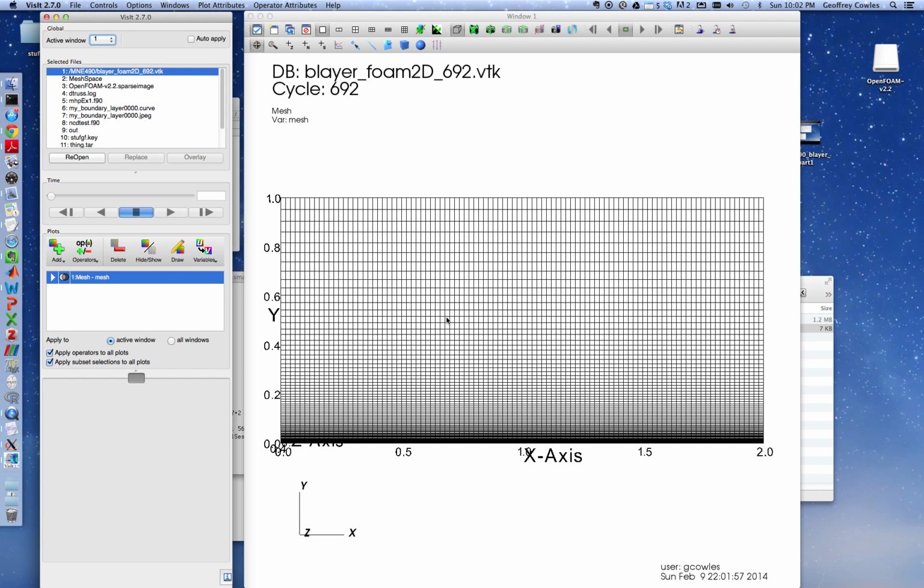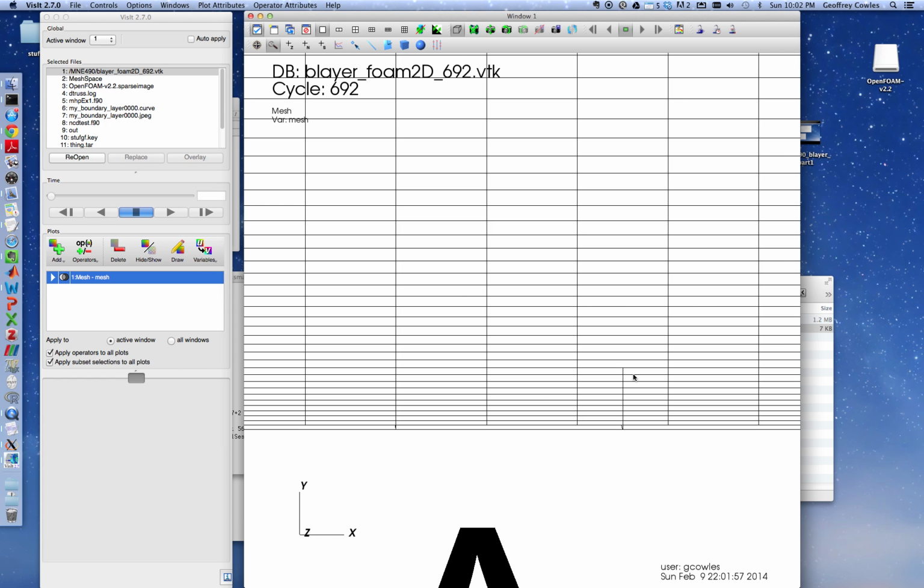See, viewed from the side, you can see what I did is I scrunched it down near the bottom boundary layer. And basically in each of these volumes, let me zoom into them. There's a little looking glass up here for zooming. I'm going to zoom in just somewhere down here. And this is actually the axis you're seeing here, but you can see these little cells near the plate.